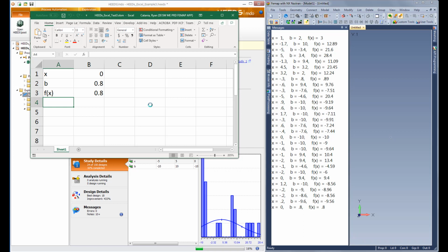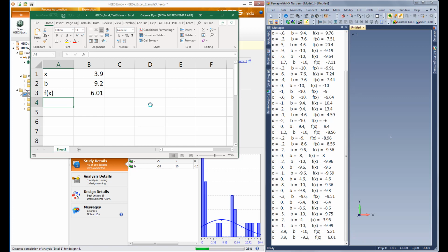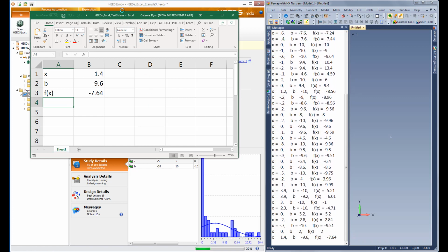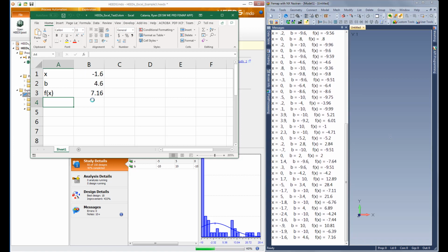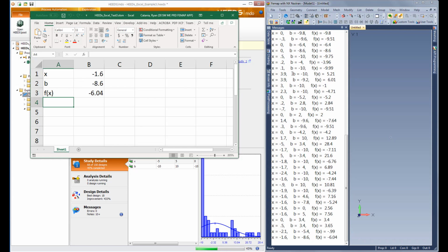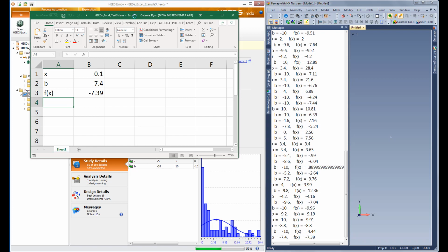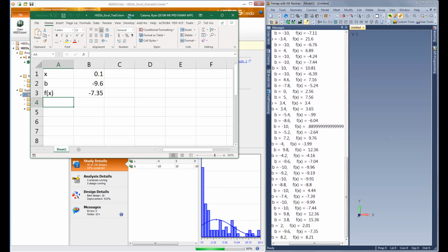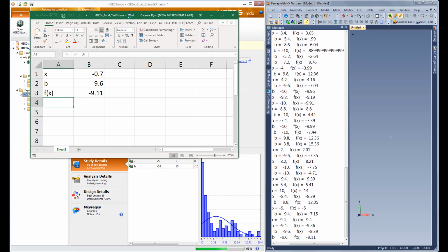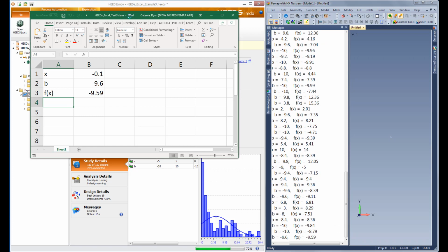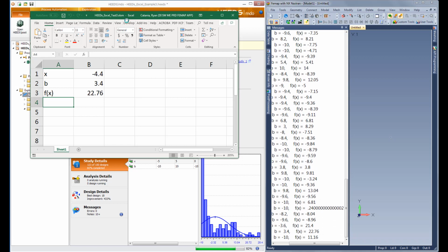This looks like to be a solid foundation to start with. There's probably more we can do in terms of optimization, locking the screen of Excel. Again, hiding the Excel process so that the GUI does not have to update would produce marginally better returns. FEMAP itself could also probably be hidden, or at least in a locked state so that the graphical user interface doesn't have to be updated until everything is complete. But I think right now this is a way to utilize HEEDS, talking repeatedly to the same processes without having to close and reopen each time.